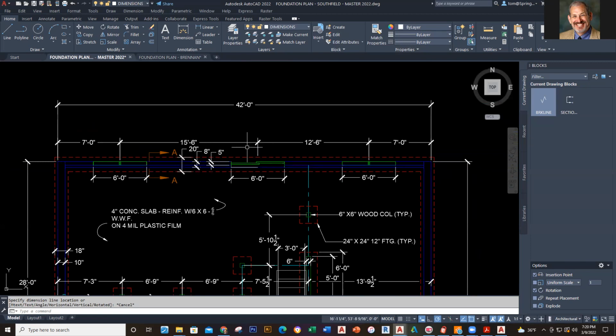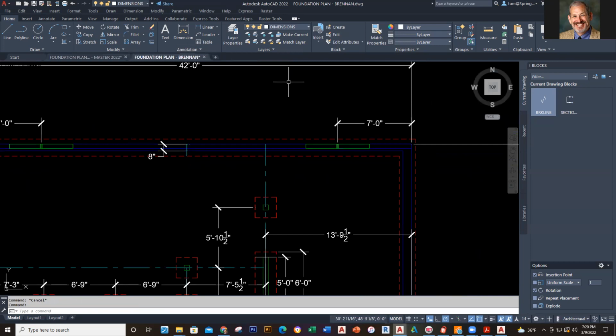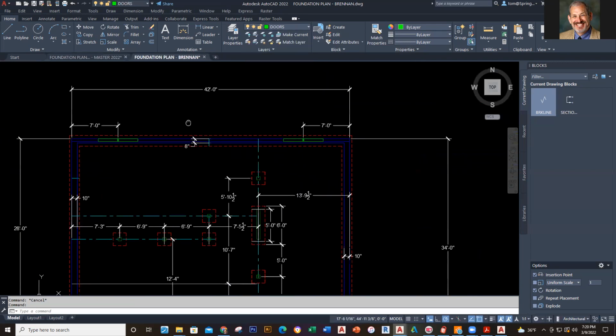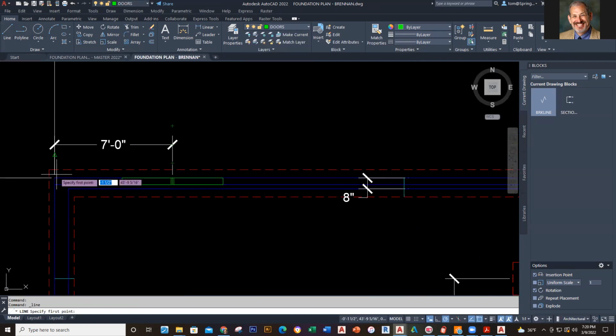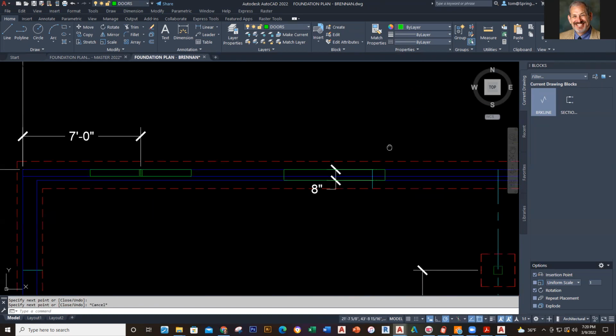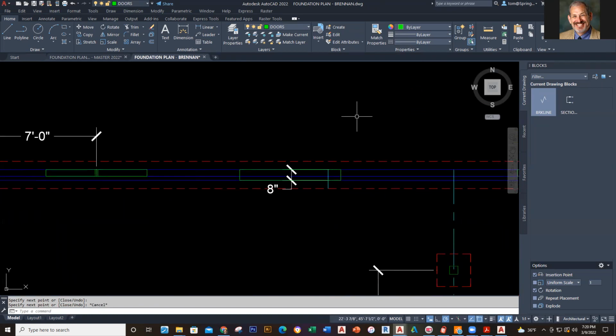So what I'll do is I'll put the 6 foot opening at 15'6". I'll do that first. So first of all I'll go over to here, and I will create the door by going over from this line over here, 15'6" here, boom, like this. And I'll go ahead and drop it here, or 6 feet. Then up. Okay, and then at that point, we'll go ahead and put those in there. And so we said that they were 3'2" by 2 inches. So make a rectangle.